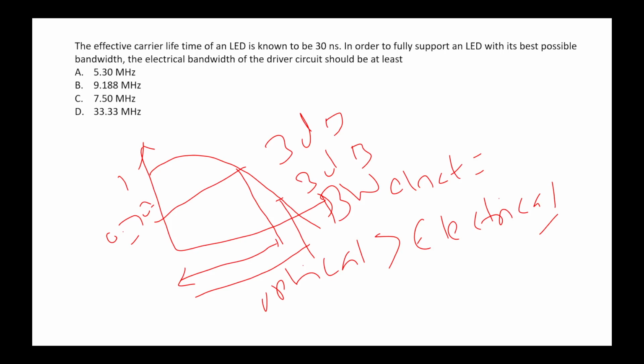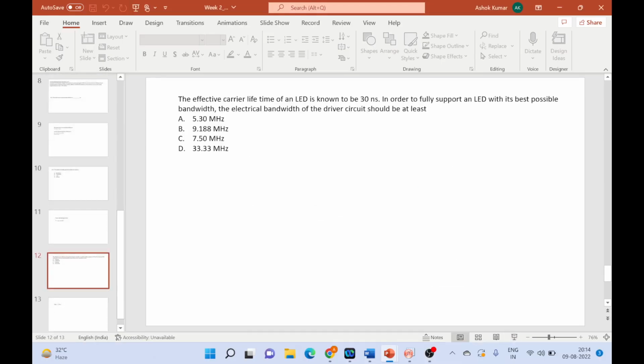Someone asked how to calculate the slope efficiency. In the case of a laser, we have to plot the output power versus the input power, and through that we do a linear fitting. In MATLAB you can plot that graph, or in Origin or Excel.